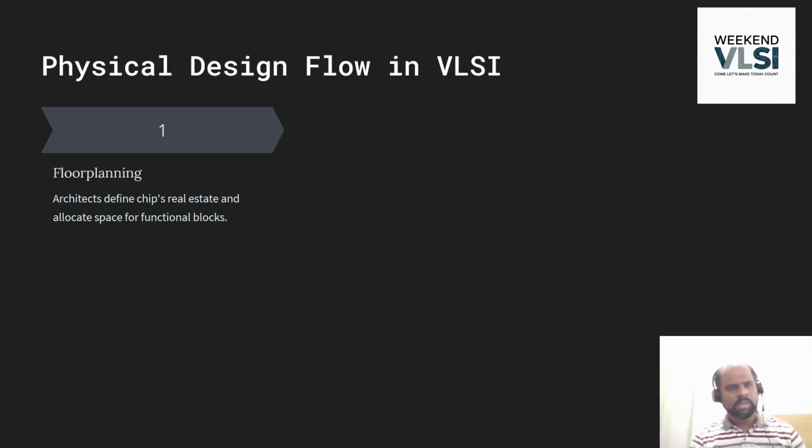The first one is estimating the size of the floor plan. Your X and Y axis you need to give, or you need to give the utilization for that block, or there may be different sites. You may have 5, 6, 7, 8, or different sites. How many sites are you specifying? How do you specify the channels? Many of these sites may be pushed down from the top level. Very few people do it at block level. At block level generally, when there is a rectangular floor plan, we do it. A rectilinear one is always pushed.